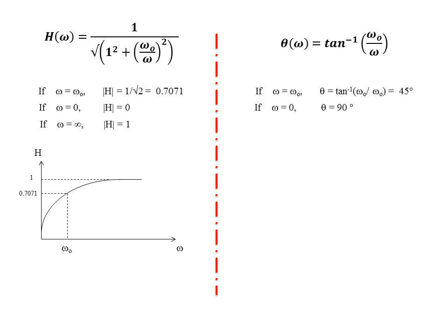If it's 0, then our theta will become 90 degrees. And if it's infinity, then our theta becomes 0 degrees. Right, this will make a phase plot something that looks like this. Starts from 90 and goes to 0 at infinity. In the middle, you will have something like 45 degrees at a frequency of omega naught.